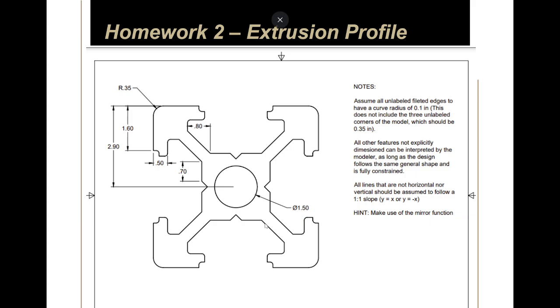But the main advantage is they're all standardized, and they have these little profiles that you can insert hardware into. There's something called a T-nut that will fit in here, and then you can add nuts and bolts into it. So you can add accessories or whatever you want to your aluminum extrusion. It's great for prototyping if you're ever making stuff. This stuff's really popular.